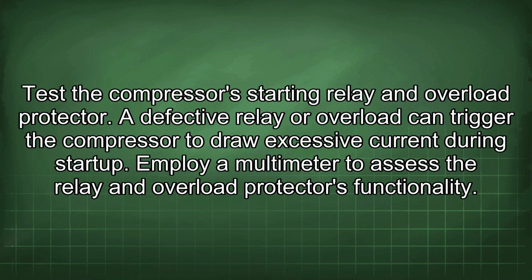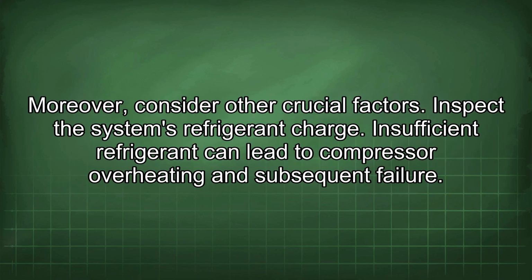Test the compressor's starting relay and overload protector. A defective relay or overload can trigger the compressor to draw excessive current during startup. Employ a multimeter to assess the relay and overload protector's functionality. Moreover, consider other crucial factors.